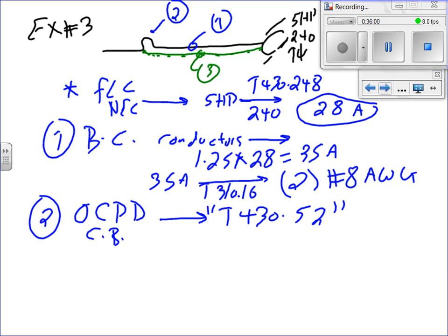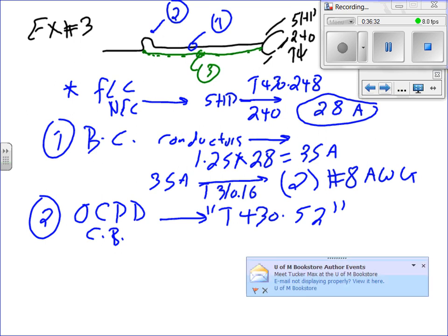But even with this, because I have no idea who the manufacturer of this circuit breaker is, GE, Siemens, Square D, or of this motor at the time of the design, what I would do is go with the worst case scenario and follow what the code says. When you get more information about the motors, you can readjust your design and go for a lower overcurrent protection device. You can if you know it, but at the moment of design, most of the time we don't.